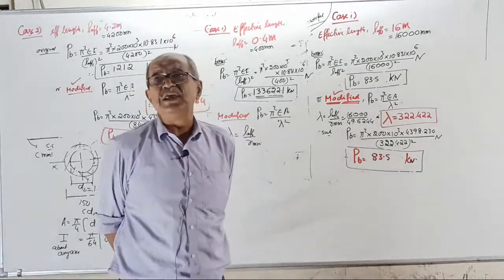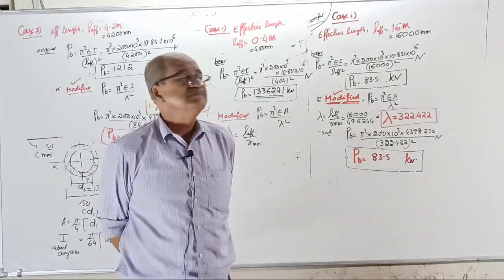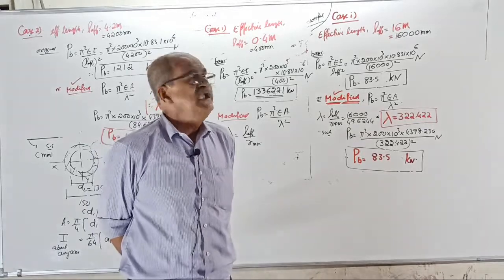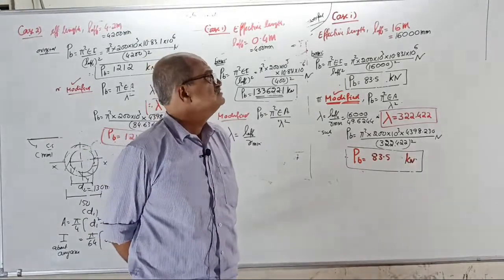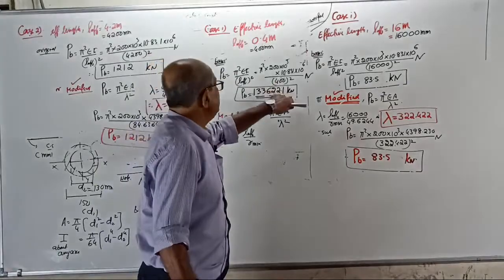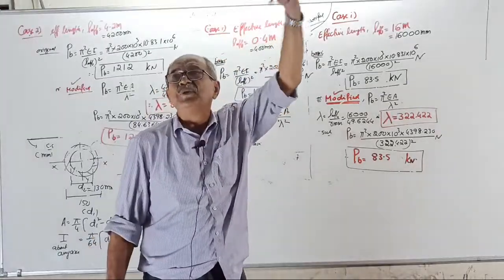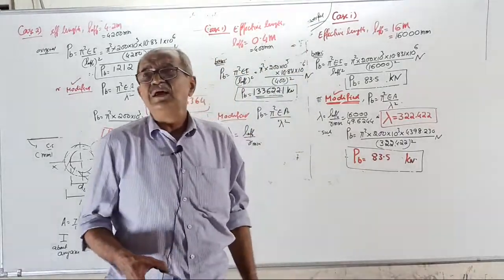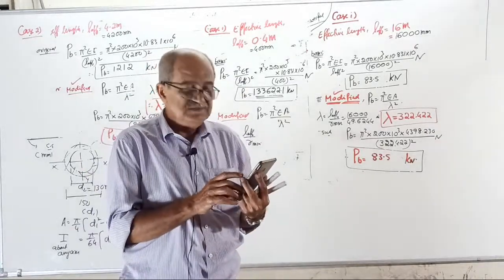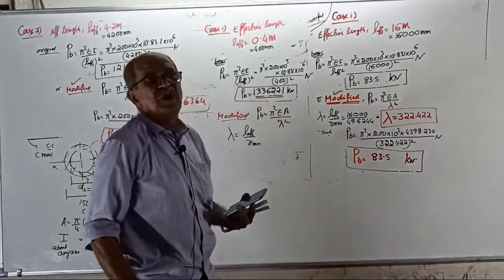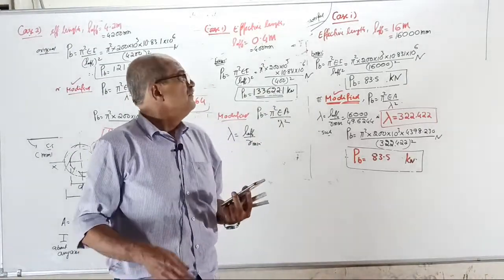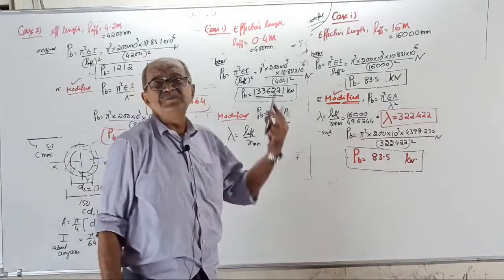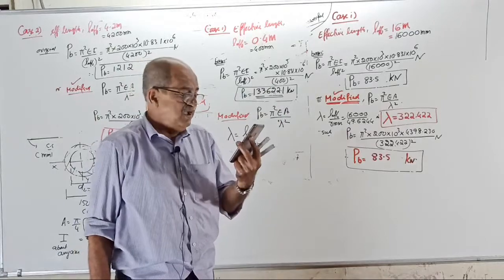When you find area of steel, suppose the number of bars. Instead of getting 3 bars, if you get 300 bars or 0.3 bars, you can make out something is wrong. But if this value is somewhere in between, and later you get an odd value, you will not be able to know what the mistake is. Since it is the final answer, you can make out. But if it is an intermediate value and you go somewhere else, then such mistakes are done. You should be extremely careful. It is a dangerous mistake.